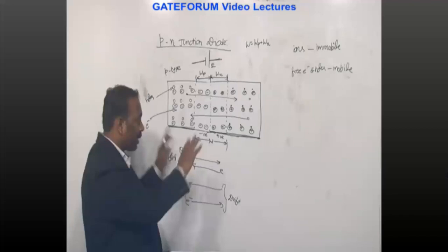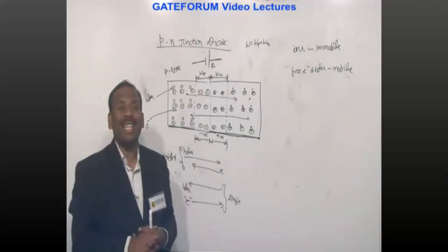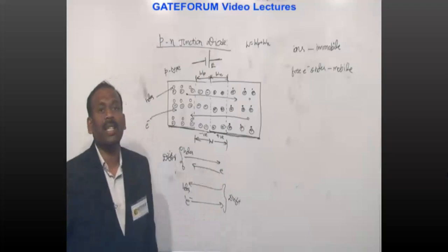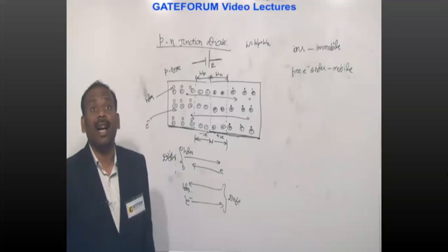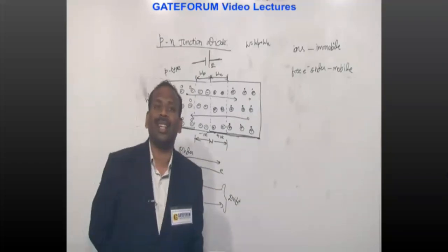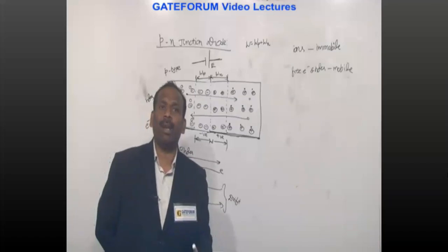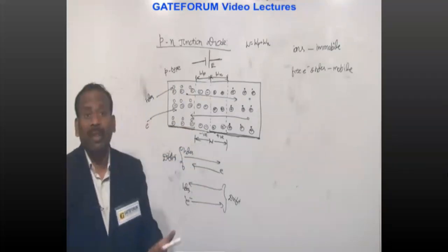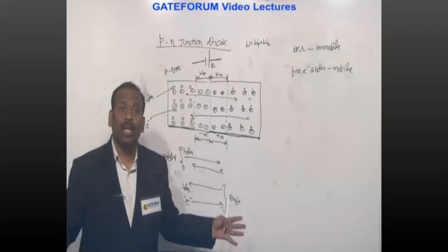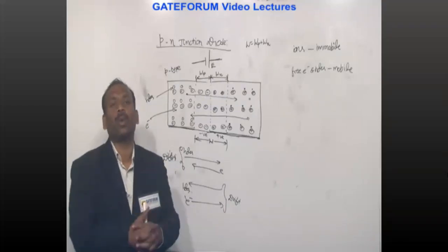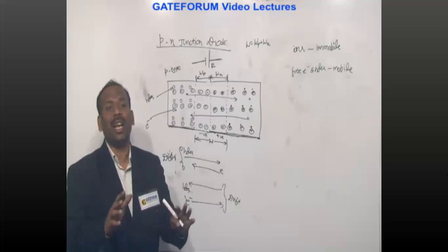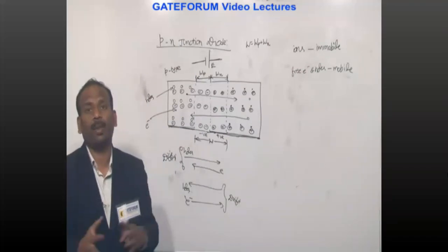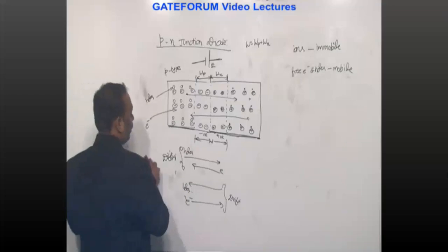Therefore, under unbiased condition, that means externally we have not applied any external DC voltage. See here, it's left half stage. We have not applied any external DC voltage. This is called unbiased. Under unbiased condition, the internally developed electric field will constitute some drift current. Because of diffusion, some current will exist. Both are in the opposite direction and the magnitude will be equal. Therefore, current will be zero initially under unbiased or open circuit condition. Clear that point? Now comes to our next point.